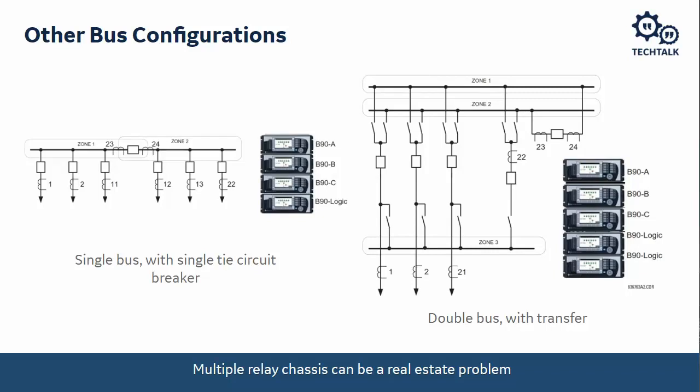Now, for a big bus with up to 24 breakers connected to it, that might look like 3 or 4 relays there, at least 3 relays to do the 3 phases. If I need to share logic across those relays, I may do that with a 4th relay, like I show here.